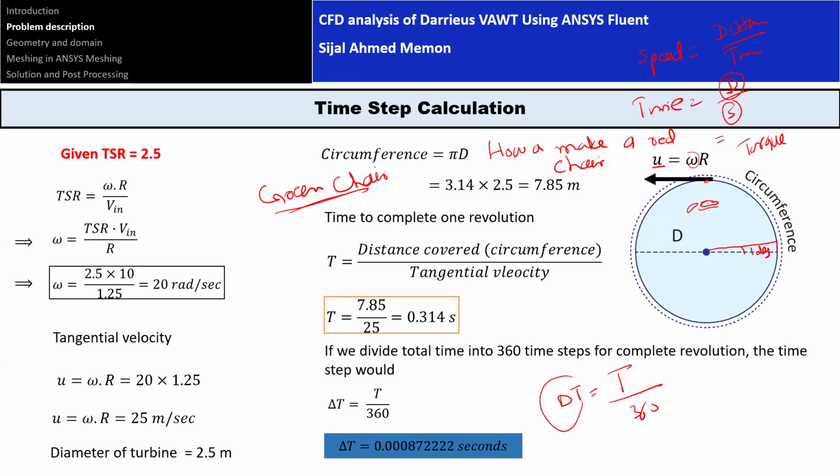So understanding the problem is a very important thing, and then how to convert that problem into numbers, and with those numbers how to get the geometry, make the proper settings in the CFD solver, meshing, and then analyzing results, and then comparing with the known data. And even if you don't have the known data, like any analytical solution is not possible for that problem, if you don't have any numerical solution from some other person, you don't have any experimental work, even in that case, you should be able to compare your results. You can have some sense about the results, what should happen with your case.